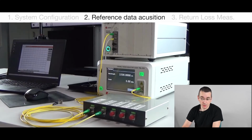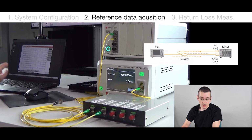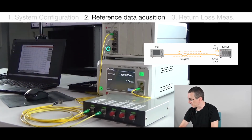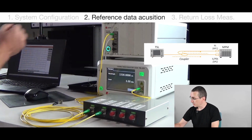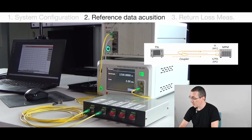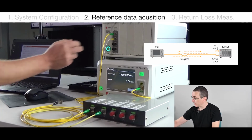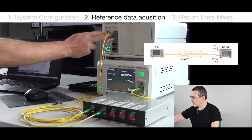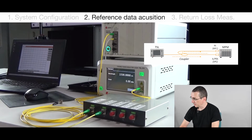Now that my system is fully configured, the first thing I have to do is to collect the reference data. For the optical return loss measurement, we will need a coupler. The first branch of the coupler will be connected to the TSL. The second one will be connected to the first channel of the MPM, and the input fiber of this coupler will be connected to the second channel of the MPM. Notice here that channel 1 is connected to an APC polished fiber, whereas the second channel is connected to an SPC polished fiber. We will see the reason very shortly.